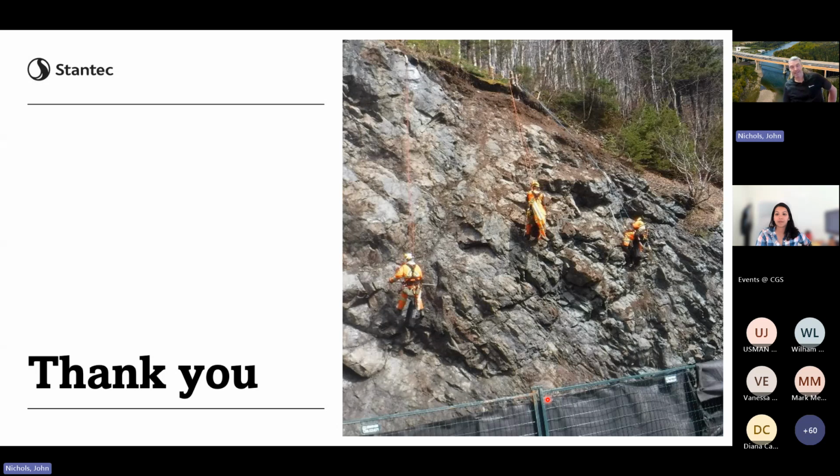Yeah. So like I said, passive bolts are not tensioned. They're relying on a fully grouted dowel to engage. And sometimes it acts in shear as well. If you take the strength of the steel bar and apply shear strength to that bar, it reacts to movement. It doesn't prevent movement, but depending on the orientation and the application, passive bolts are much easier to install. When you do an active bolt, you need to make sure that you're behind the failure plane, and then you tension it, and then you can finish your grouting.